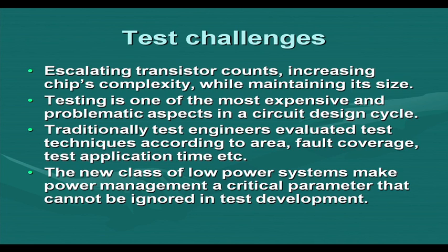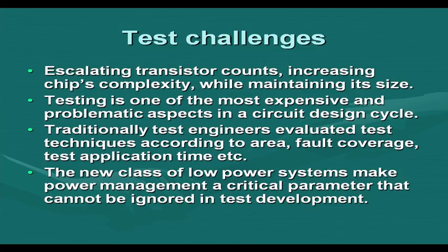test pattern set. But these low power systems make power management a critical parameter, because low power systems will have a power budget. You cannot go beyond certain power consumption. Normally the designer will tell the power budget for a system, so it cannot go beyond that. As a test engineer, we cannot apply patterns so that the budget is exceeded. So that way power management becomes an important part in the testing process also.